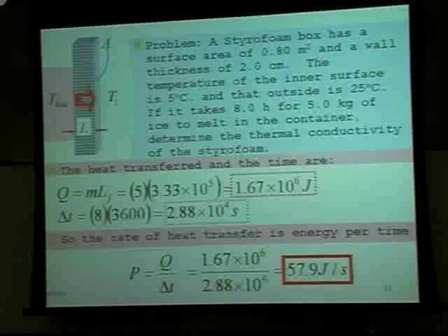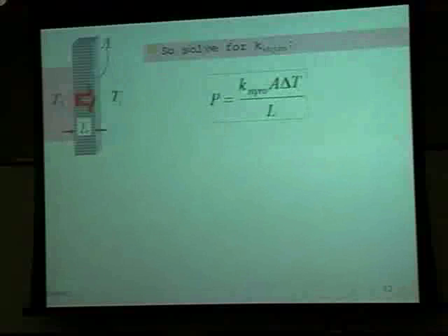So far so good. That's our power that must be transferred through that styrofoam in order for the ice to melt. Not what you really want to happen, but that's what's happening. Let's reverse engineer power equals kA ΔT over L and solve this for the thermal conductivity of styrofoam.